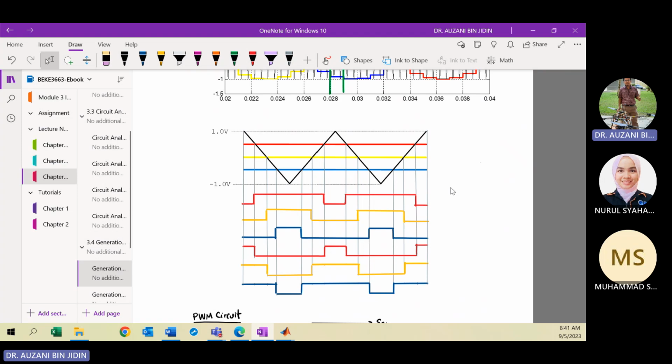You cannot consider the wave shape as plotted using continuous mode, because the waveform is continuously and dynamically changing. So in order to analyze the operation to generate the switching state, you have to consider the generation of the sine wave in discrete mode, discontinuous mode. So at one sample, or for this interval, you get a straight line wave shape for VA, VB, and VC. Clear?